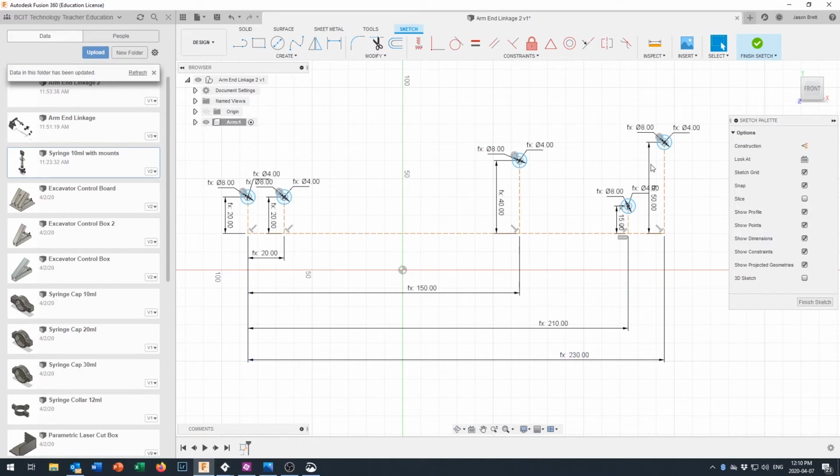We now have our sketch fully dimensioned. Like I say, we are going to come back later on and use some of these dimensions. We're going to create a bigger circle around there to have a nice radiused corner, and create a solid piece of what would probably eventually become MDF cut on the laser cutter, or hardboard cut on the laser cutter. You could make it out of sheet metal, print these dimensions out, print your profile out, cut it out with shears, and hole punch your holes. You can make it nicely out of sheet metal. Whatever technique you want to use to make it, you can do. Heck, you could 3D print it if your 3D printer was big enough.